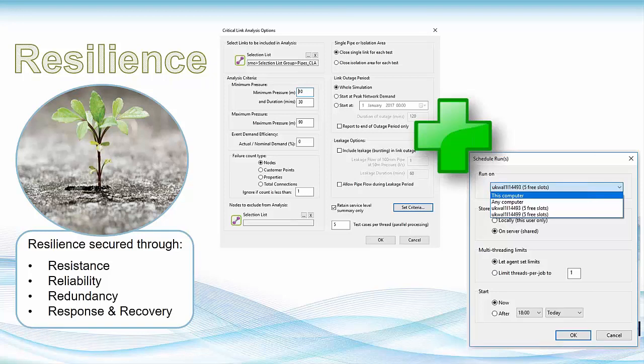So as I was saying, this is quite important information because it really defines the redundancy of the pipe. So when we talk about resilience, this is an important type of information, but a lot of people also do risk analysis on their system, and as you know, risk can be defined by the product of likelihood of failure and consequence of failure. Likelihood of failure can be defined by looking at the pipe burst history or age of the pipe, material of the pipe, but when we talk about consequence of failure, really the number of properties affected by an isolation is very important information to know.